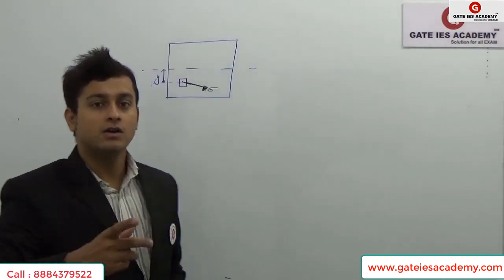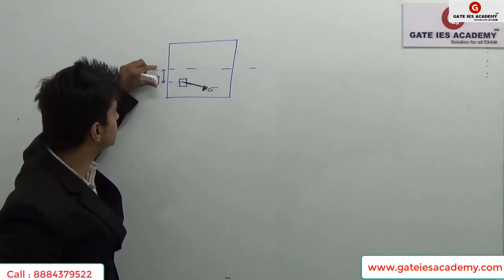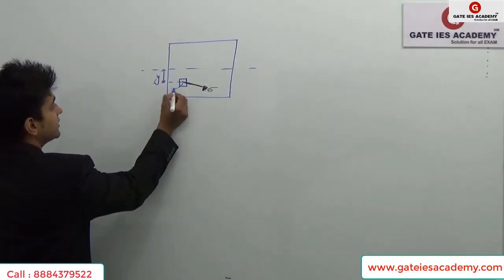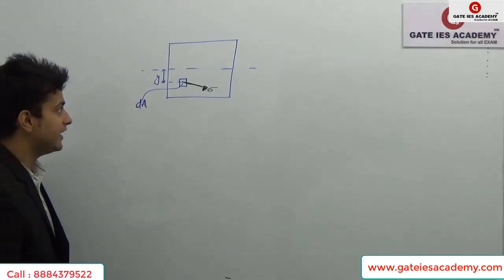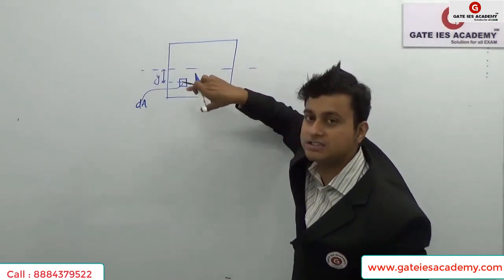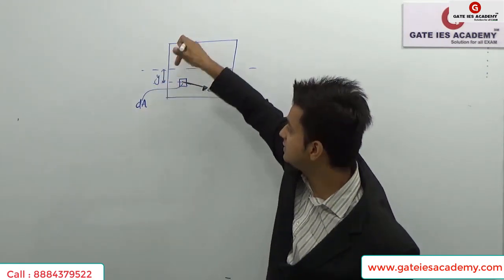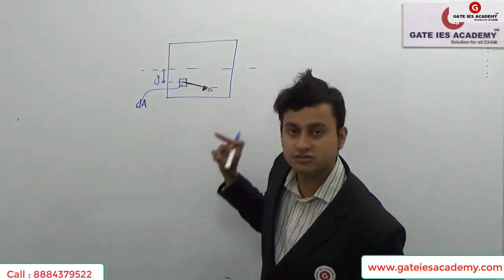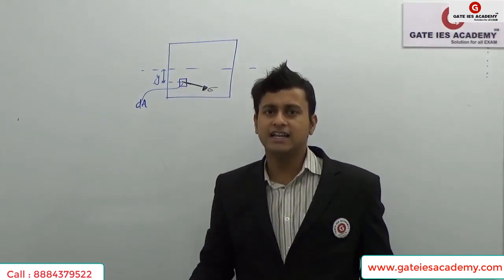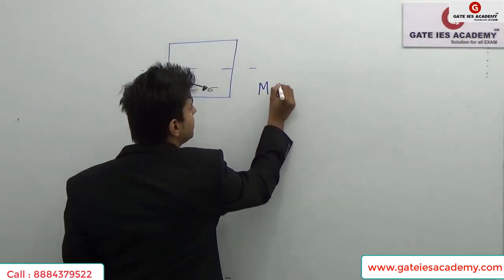Okay students, now let's move forward to derive the whole bending equation. At y distance beneath the neutral axis, I have taken a cross-sectional area of dA magnitude. If I want to calculate the moment generated about this neutral axis due to this stress, it is the force multiplied by the distance, that is y. We have stress; if I multiply it with the small area dA and integrate throughout the system, I get the total net bending moment, which is M.